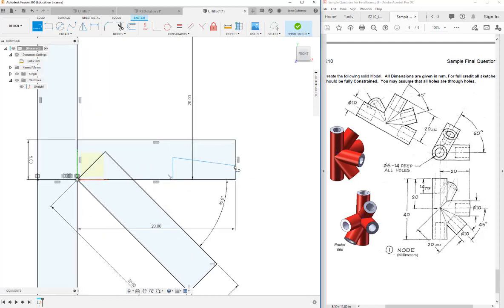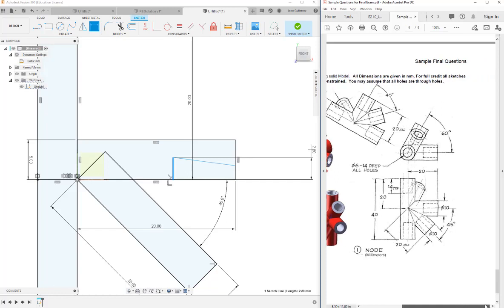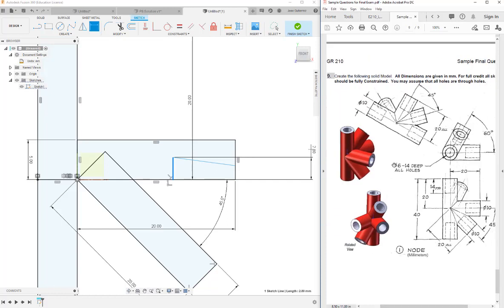And I don't want to snap to that midpoint, so this is not what I'd like. I'm going to dimension this as being that inner diameter was given as, let's see, let's look for it over here, drilled to a depth of 14, and I am not seeing my inner diameter specified. Oh, there it is. Diameter of 6 millimeters.